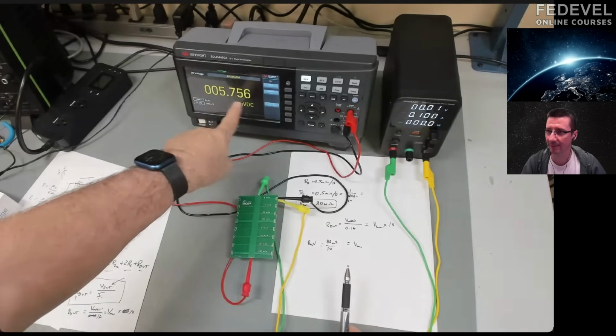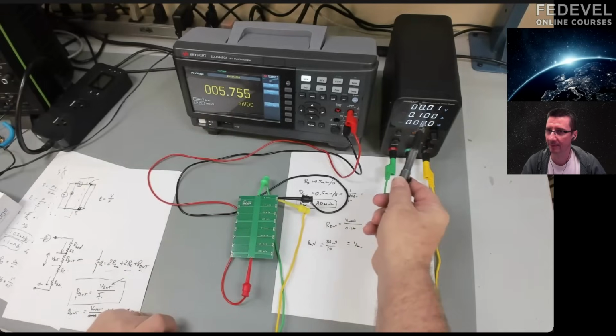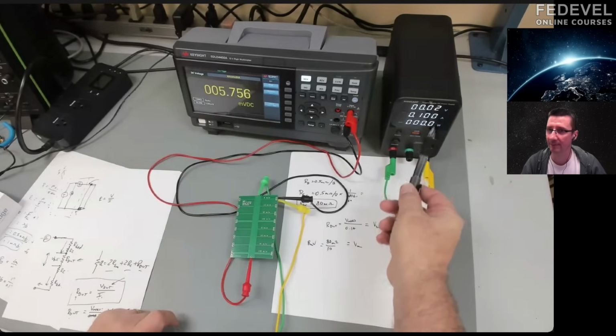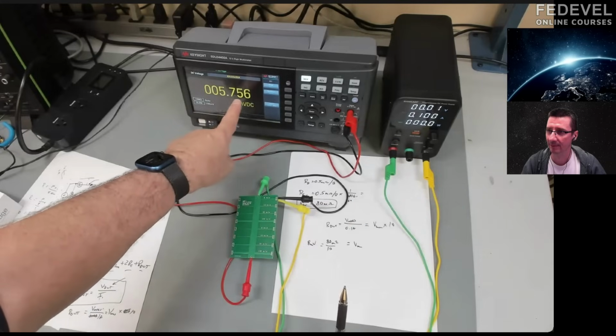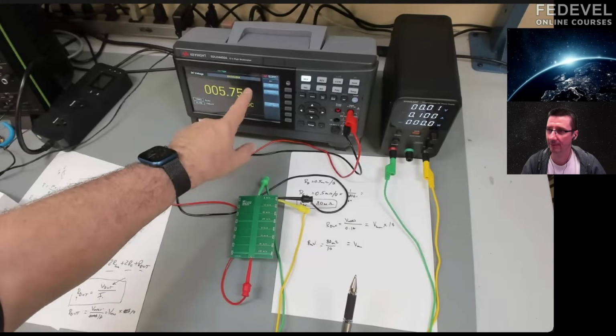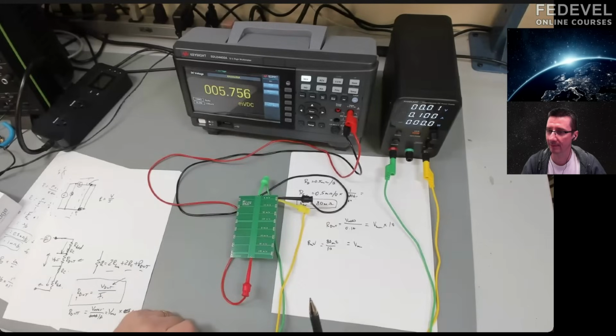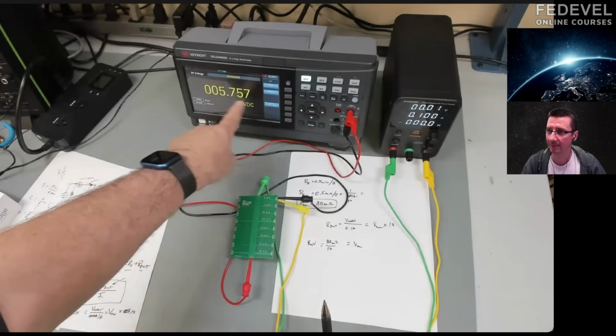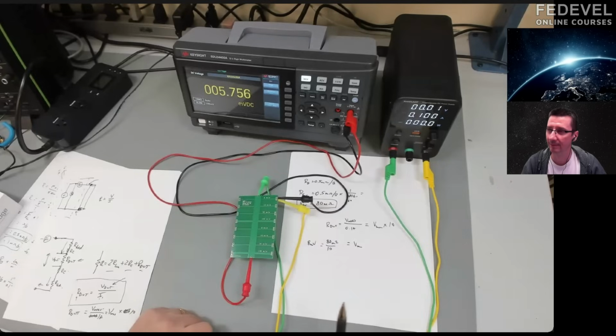I think this is a pretty accurate number because I think the uncertainty in the current is about 1%. And I think the accuracy of the voltage is better than 1%. It's plus or minus the last couple digits over here. So I think that this is accurate to about 1%. And so I think it's a good number. It's just lower than we expect because the sheet resistance is smaller than our simple estimate of 0.5 milliohm.